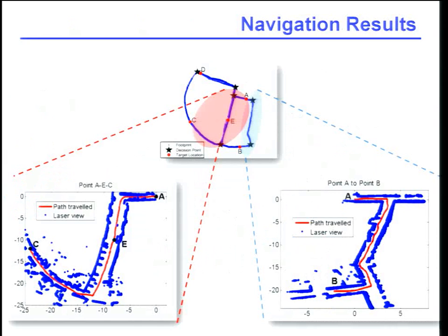These are the navigation results. In the middle, we have the cognitive map. It's not very clear here. On the right, this figure shows that the robot successfully navigated from point A to point B and the correct decision is made at the 2 junctions encountered along the way. The left figure shows similar results, but for navigation to multiple destinations. It's also shown in this paper that the robot is able to navigate a farther distance and with a faster speed, thanks to the lower computational load of the proposed algorithm.